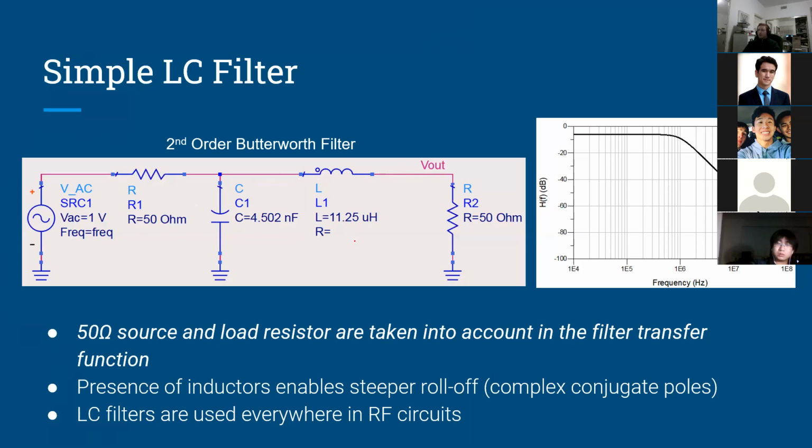All right, so if you look at the filter response, you'll notice something slightly different. We're still at minus 6 dB here, which is to be expected at low frequencies. However, the roll-off of this filter is no longer minus 20, now it's minus 40 dB per decade.